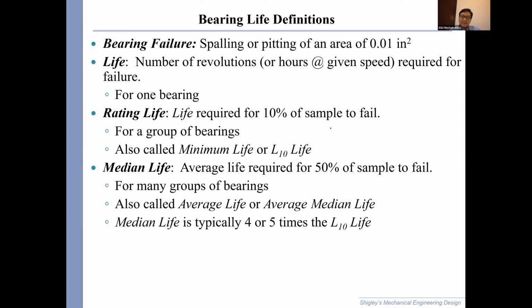Remember the C10? The C10 is the life required for 10% of the sample to fail, probability-wise, after a rated life, let's say 1 million cycles. SKF uses 1 million cycles, with 10% failure. So that's the catalog load rating C10.